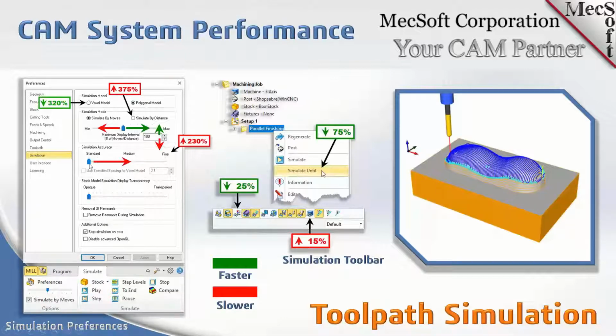Again, there's a slider for accuracy: standard, medium, and fine. Just be cognizant that if you jack it up to the right, you're going to slow down your simulation time. It could be as much as 200 or 300%, two or three times longer, using the finer simulation. So if you don't need to, there's no need to.